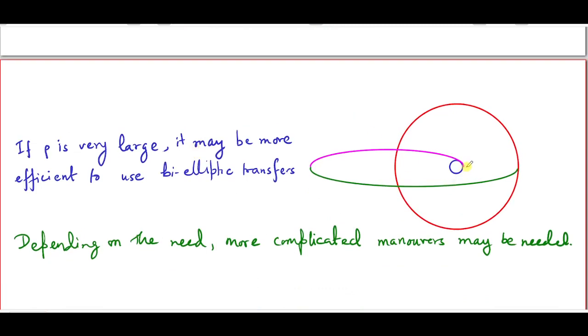Here, you do an impulsive change of orbit, say for a particle moving in this small circular orbit, of course small in this scale. You would turn the thrusters on at this point and put the particle in a larger Hohmann-like orbit, but this time the apogee of that orbit is not at the target radius, but it's actually quite further away.